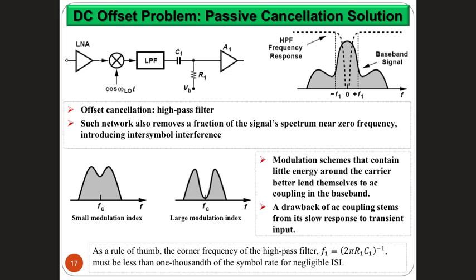This filter, which is very narrow at a certain frequency and accepts all other frequencies, is called the notch filter. It's a special type from the general category called band reject filter. So it's rejecting a certain band and accepting all other bands. But in the case where it's very narrow, it's called a notch filter.